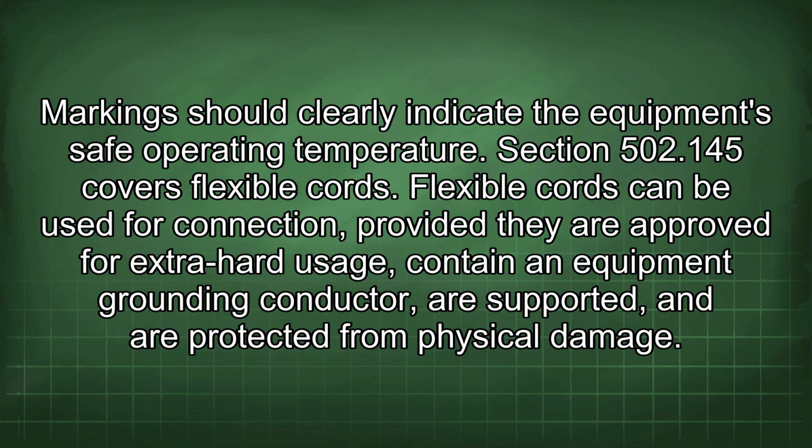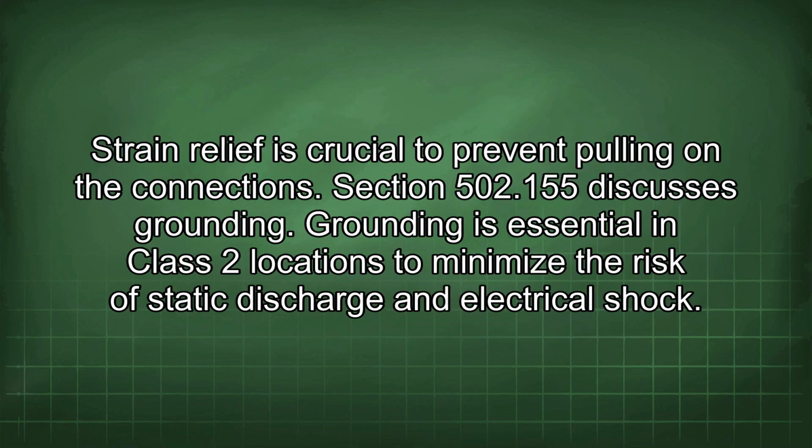Section 502.145 covers flexible cords. Flexible cords can be used for connection provided they are approved for extra hard usage, contain an equipment grounding conductor, are supported, and are protected from physical damage. Strain relief is crucial to prevent pulling on the connections.